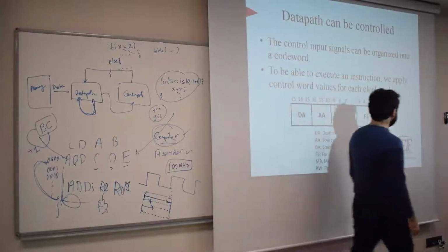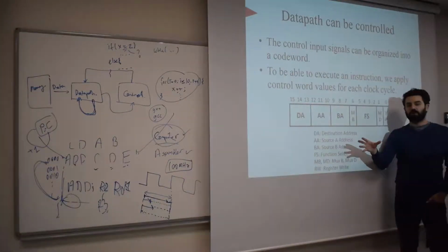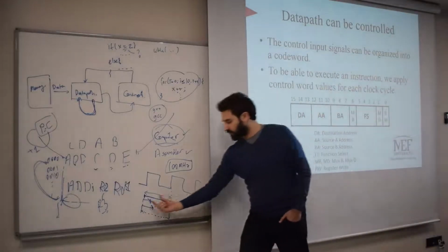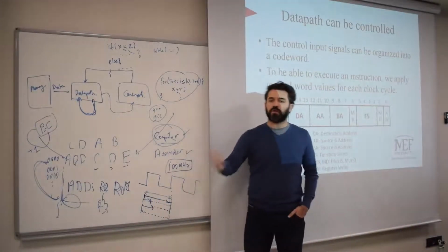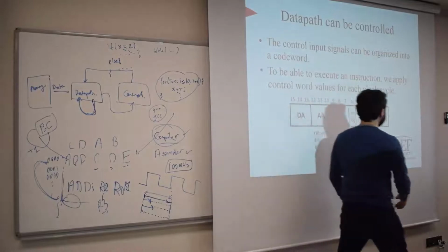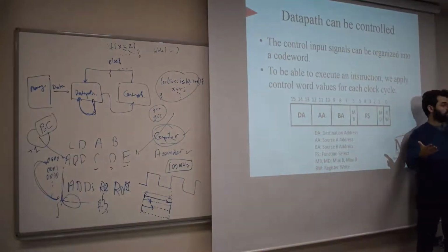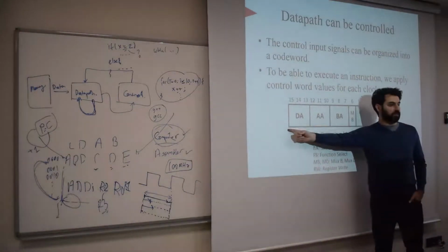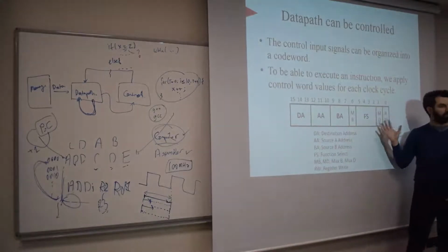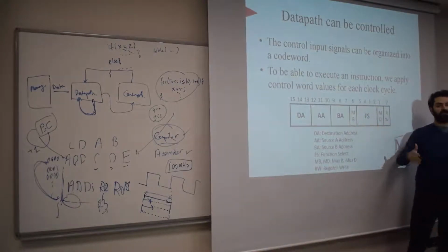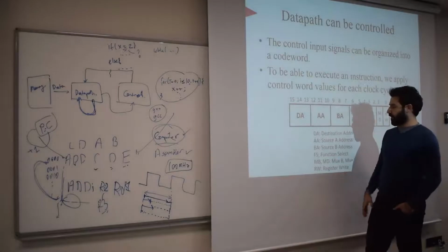And in that period, while you're executing these instructions, add operation, simple XOR operation, other logic operations, you also have to generate through a control circuit these control bits, 16 of them, and supply those 16 bits to the data path so the data path can execute the corresponding operation.